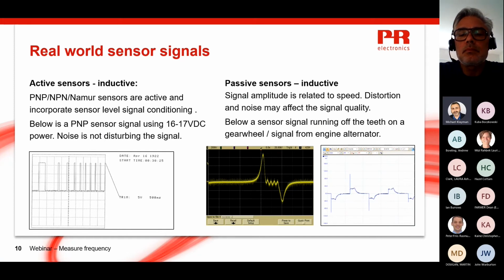Sensors can have a wide range of typical signal levels. The active sensor on the left produces a high peak to low peak voltage of 5 volts. The passive sensor on the right produces a 200 millivolt peak-to-peak signal up to an 800 millivolt peak-to-peak signal. With low-level signals, it is important to do what is necessary to avoid noise as much as possible.